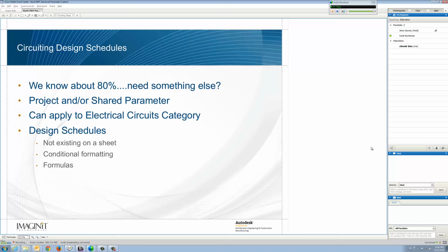So currently with Revit MEP, once we hit that 80%, we get the warning that pops up and tells us, hey, you're exceeding 80%, and you can go on. But at no point in time do you know where you're at related to that 80%. I don't know if I'm at 70, 75. I don't know if I'm at 125. If someone has already worked on that circuit and accepted it, not until I go to edit that circuit am I going to get that notification.